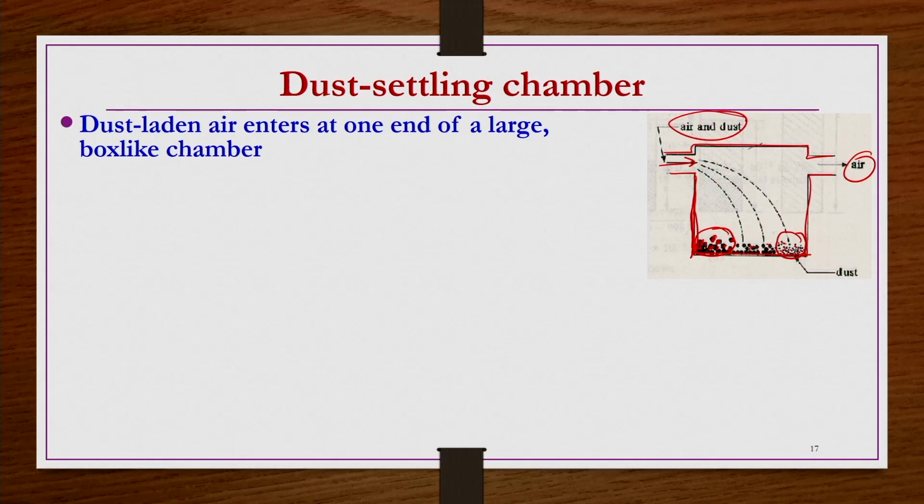So, this is the basic concept: solids settle at the bottom, and clear air passes through from the top. This is the basic principle. Here again one has to do the proper calculation, what should be the height of the chamber, what should be the length of the chamber, and what velocity the air should come in at, all those calculations one has to see, so that these particles settle in this manner.